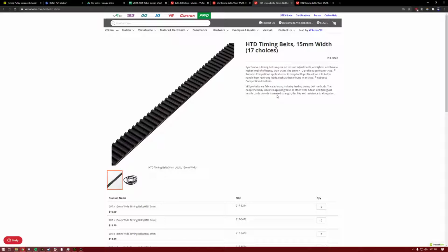That's basically the number that determines the size of the teeth. Like on a number 25 chain, you have a 1/4 inch pitch. So every link of that chain is a 1/4 inch apart, right? There's a 1/4 inch spacing. Similarly on a belt, a full, not link, but basically cog of this is 5 millimeters. You can look up all the math that you'd need to calculate that from two pulleys and the distance, and I would highly encourage you to do that if you've never looked at that. But in the vast majority of cases, what you're actually going to want to do is use a calculator for that.